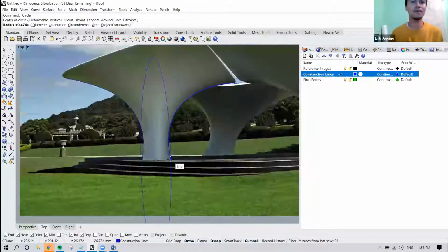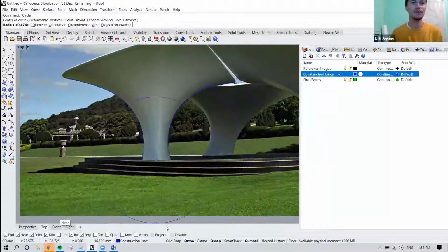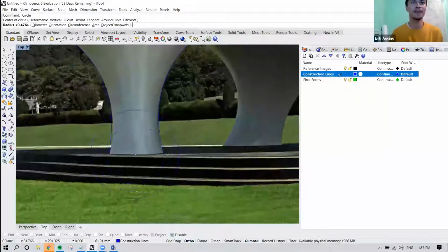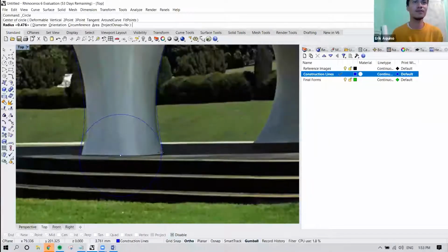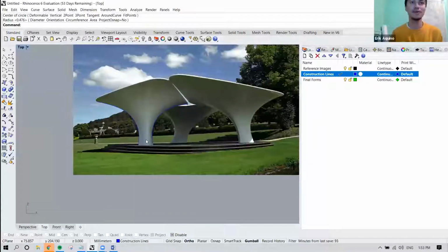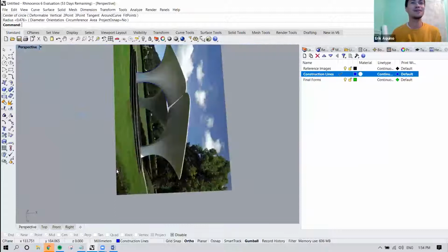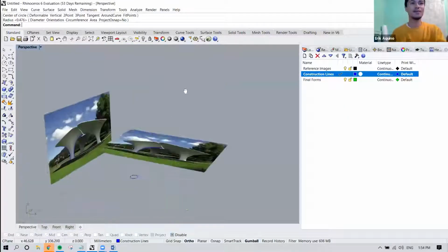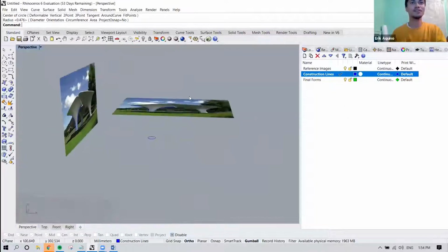This is somewhat in the middle, so I'll start off by creating a center point, and so here maybe we don't want to have snaps on. So here I'll turn snap off. It's all going to be freehand, and we're just going to roughly determine where the circle is. And the reason why it's hidden is because we're above the working plane. So again, we should probably adjust this so that it's below our working plane. So we could select our objects, our curves, and our reference plane and drag it down.